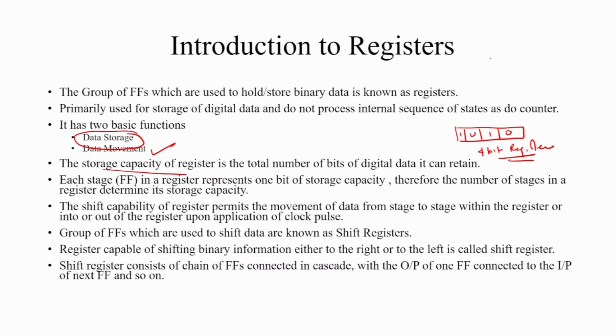Here, in the case of a D flip flop, a clock pulse is supplied, and the output depends on the input D. When input D is equal to 0, then the output is 0. When the clock pulse is high and input D is 0, then when the clock pulse arrives, the output becomes 0, or if the output is already 0, it is retained until the next clock pulse arrives.